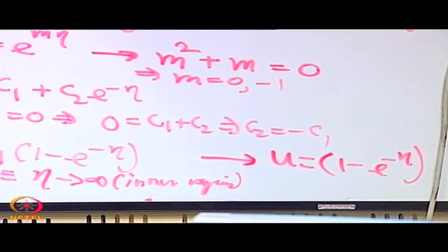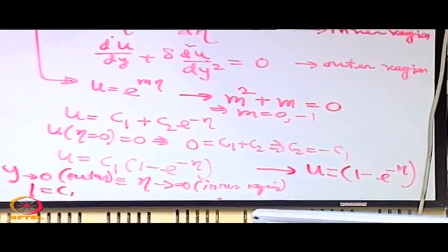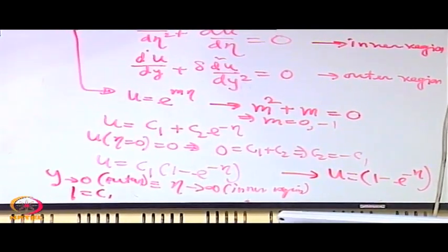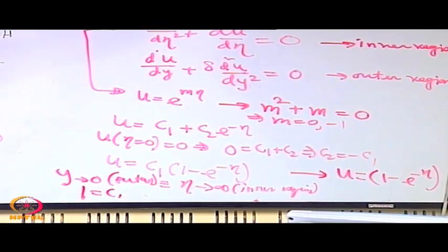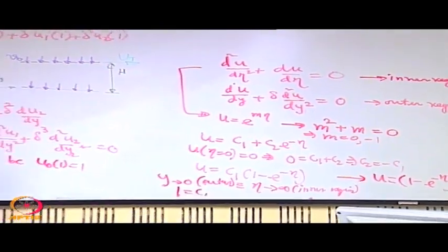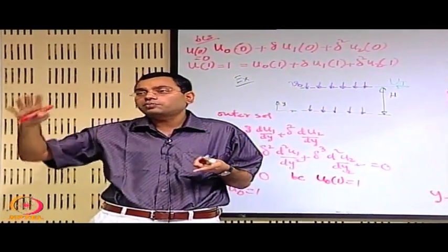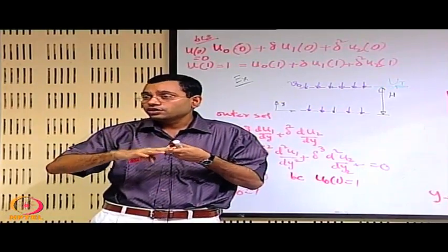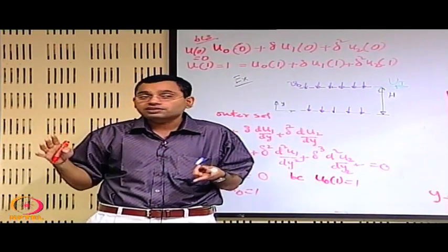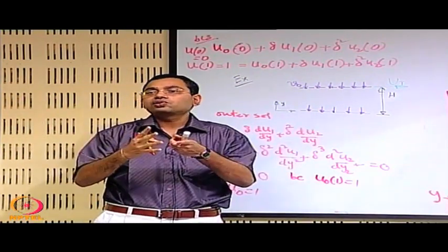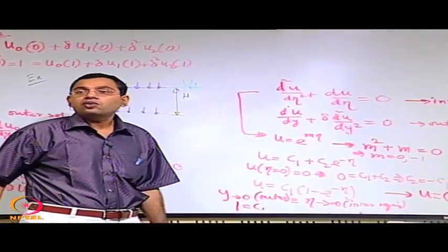Okay. So what is the trick of this method? Trick is you introduce a separate coordinate for the boundary layer which you call an inner region, where basically you stretch up the local coordinate. You use an outer region coordinate for which you may sacrifice even by lowering the order of the equation, because higher order equation you may only preserve within the boundary layer, because the second order term in the governing differential equation is important only within the boundary layer where viscous effects are important, and then match up the two solutions by considering the limiting values of the inner and the outer coordinates.